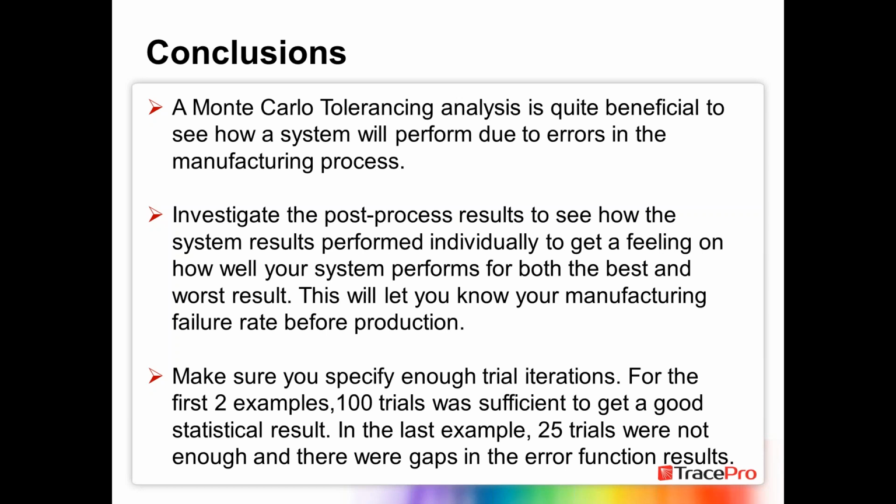If you get to that third example and you realize that the lens or the reflector is going to be a real problem for you, how can you solve that problem? Well, you might want to make the reflector a little bit different in shape, so it's not so easy for it to vary quite a bit when there's a tolerance error. Keep that in mind when you do your design: you might want to design in a performance change so that when the tolerance actually occurs, the system is robust enough to take that change.